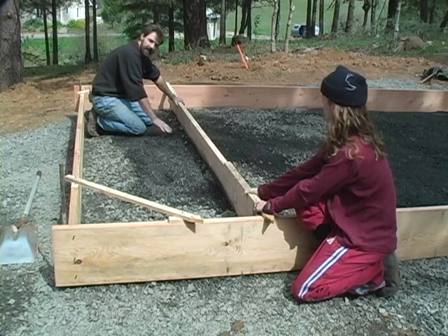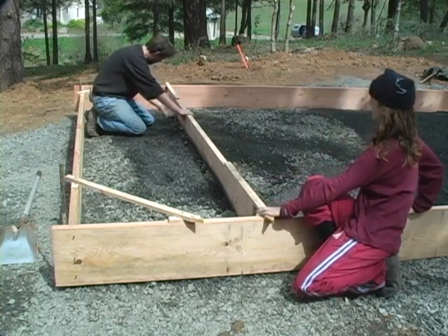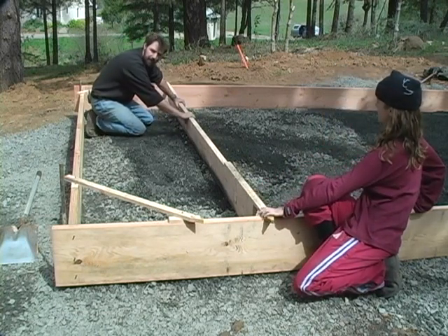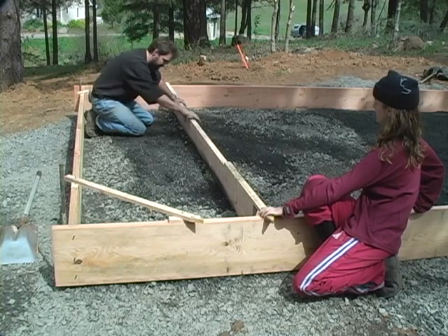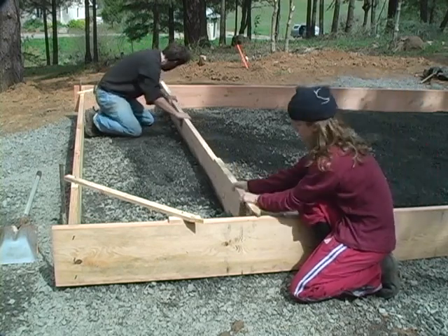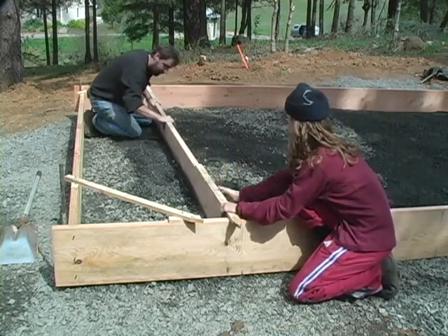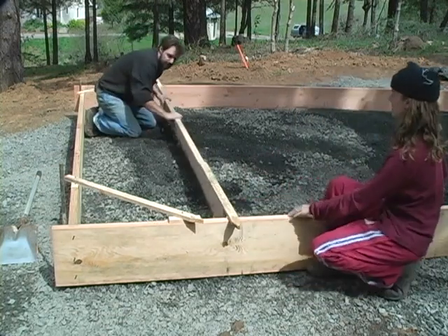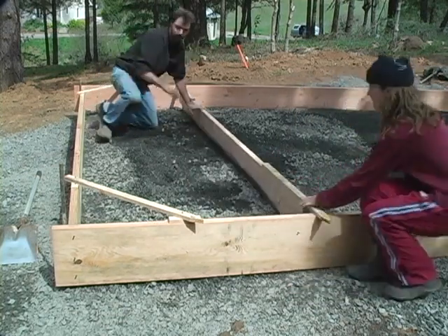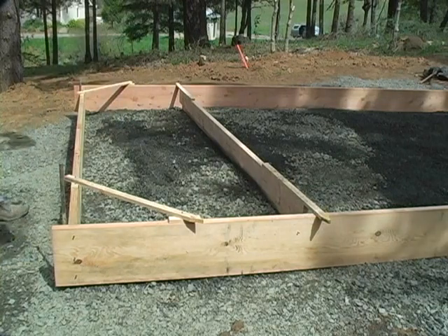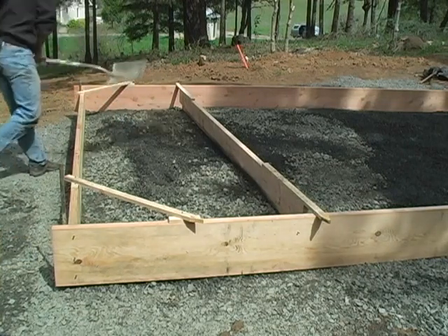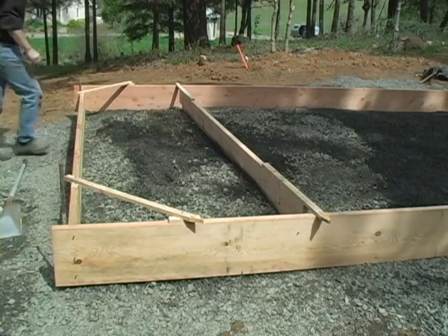As I'm getting to the edge here, I can see that there's quite a bit of hole here, so if this doesn't fill it as it drops in, we'll have to put some more material in and then screed it off to the right level. So this is really low through here. Okay, so we have 2 low spots. Let's try that.